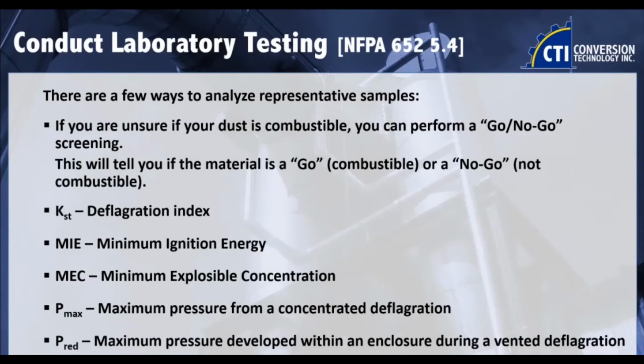Yeah, and then with this, if any of you are in timber processing or wood pellets or anything like that, we all know that sawdust is a combustible dust and flammable, but for those of you in wood, know that if you get green sawdust that has 30 to 40% moisture, that's not really a combustible dust problem. However, I have done a lot of timber facilities, and I live in Georgia. So if you have that dust, that 40% moisture that sits on your overhang for 3-4 days in a Georgia summer, that's going to drop down to about 5%, 4% pretty quickly.